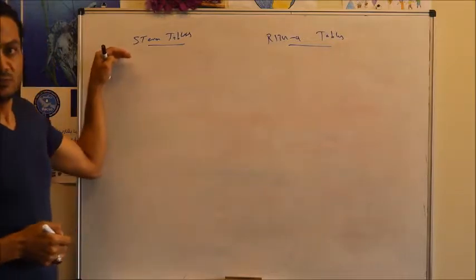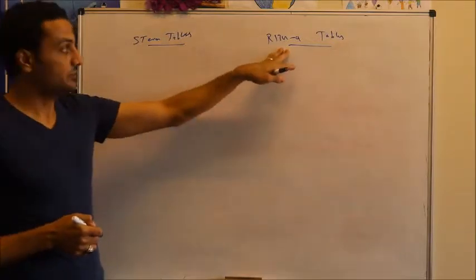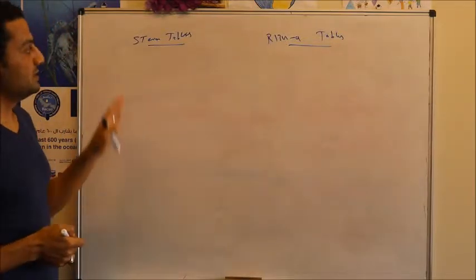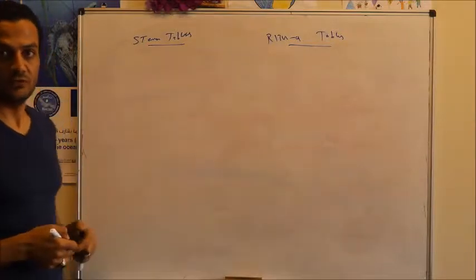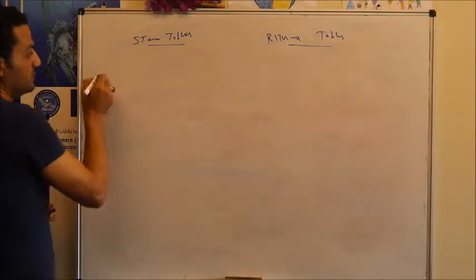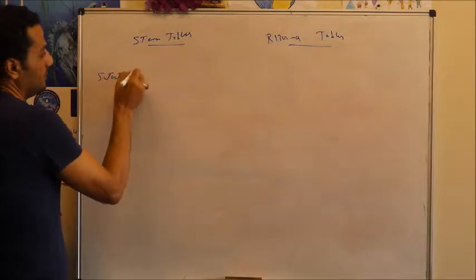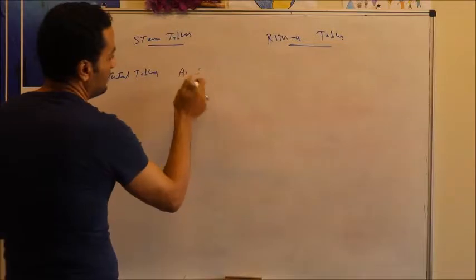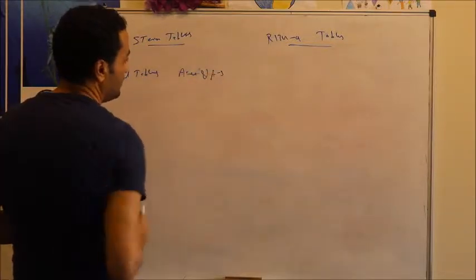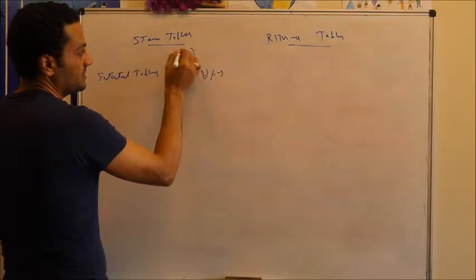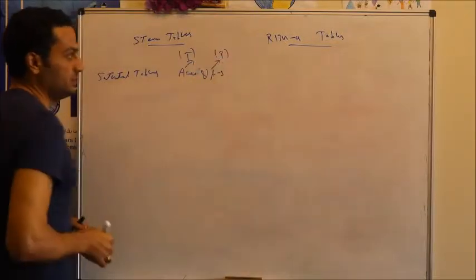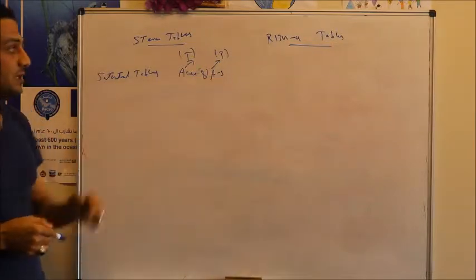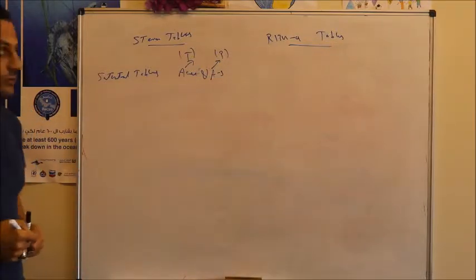The procedure for using a steam table is typically the same as the procedure for using the refrigeration table. So we'll just introduce the process of how to use the steam table, and then the same procedure can be applied for the refrigeration table. For the steam table, we have the saturation tables, table A4 and table A5. Table A4 is used if temperature is given, and table A5 is used if pressure is given.